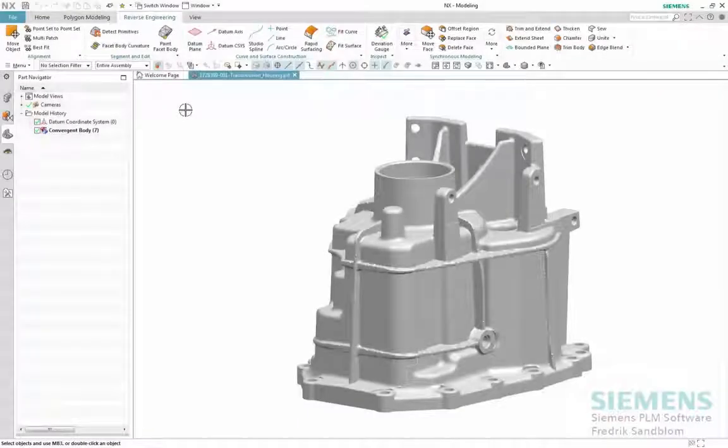Reviewing the scan data, we realize that the actual axial outlet and bearing seating area needs to be rebuilt in order to obtain maximum accuracy and also to have the correct relationships with all the other axles and gears that the specific axle interacts with. The idea here is to use material deposition or additive manufacturing to fill the entire axle seating and machine it back to its more precise definition.